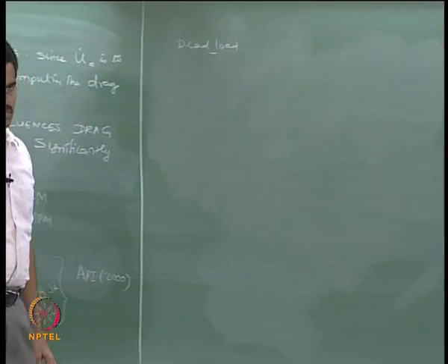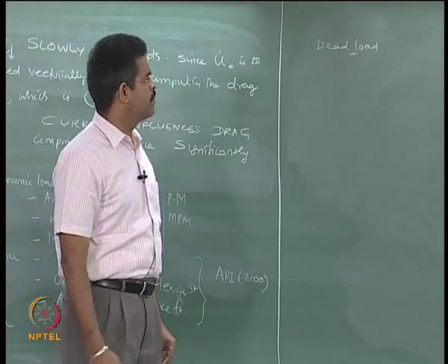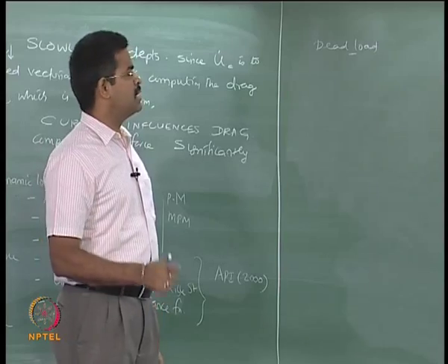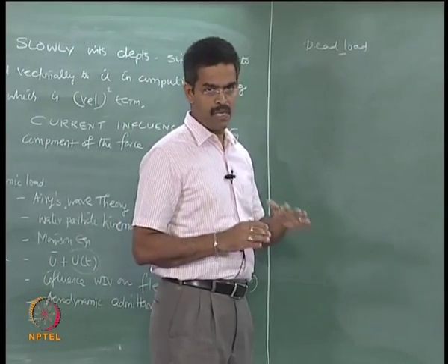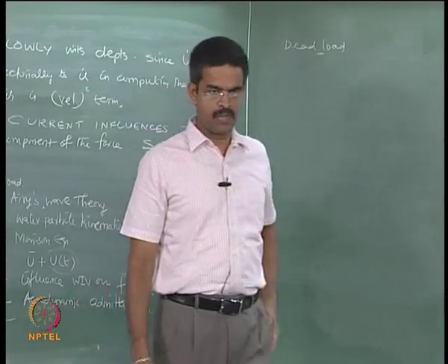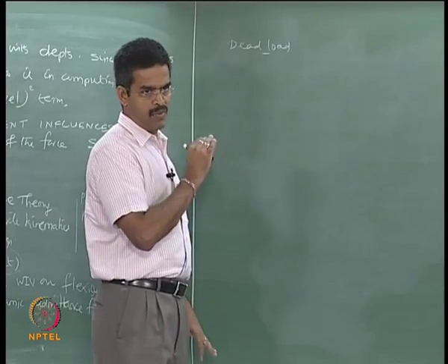What would be the dead load in terms of its intensity, and what do you understand by dead load? Very clear, explicit and intelligent definitions are given for dead load, live load and impact load in API RP. You must read these codes, the references are available on the NPTEL website of this course, but still I will reproduce them as a very brief summary here for our understanding.